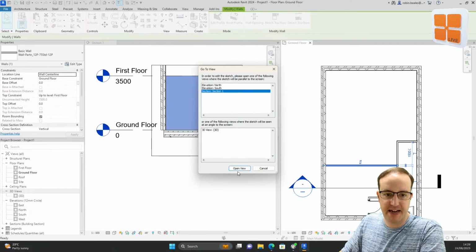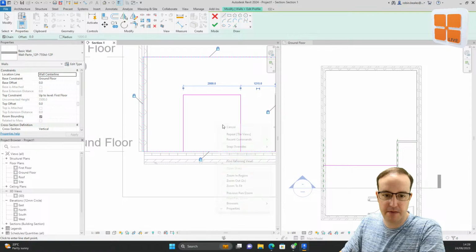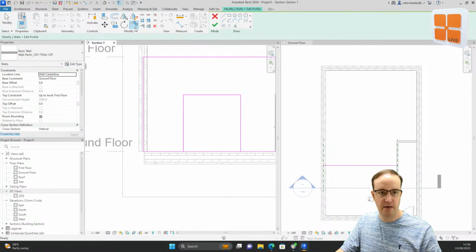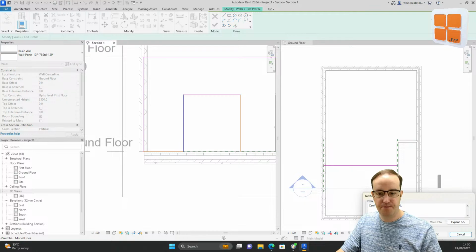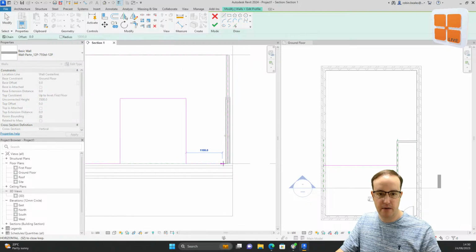I'm going to use this section to edit that wall. And I'm just going to go ahead and do a real quick mock-up of an archway or something like that. I'm not overly fussed about the sizes. Again, for the purpose of this, it's very rough and ready. But we are going to use trim to corner, TR on our keyboard. Again, remember the keyboard shortcut there in brackets. And we're going to pick up the corners of this component and then just trace in this other one over here.